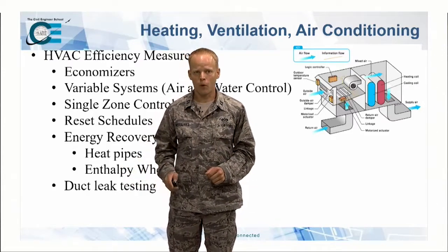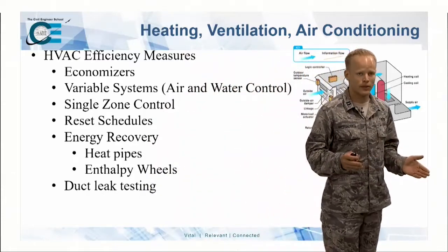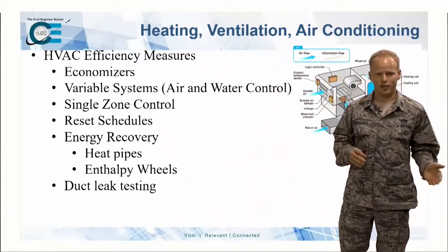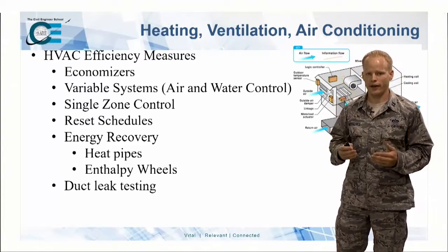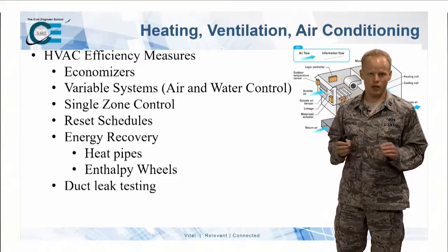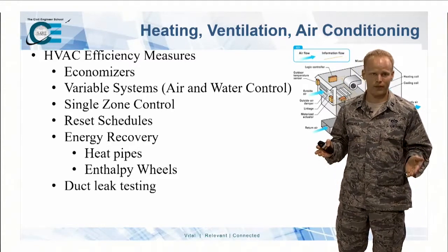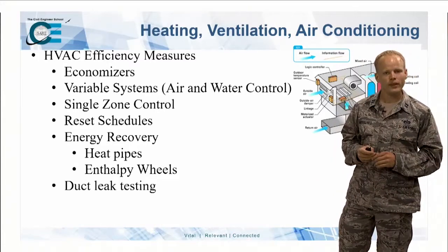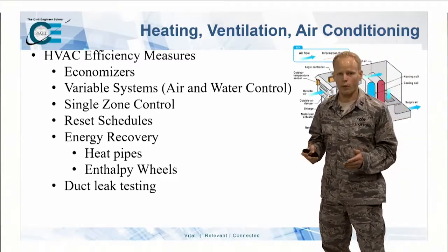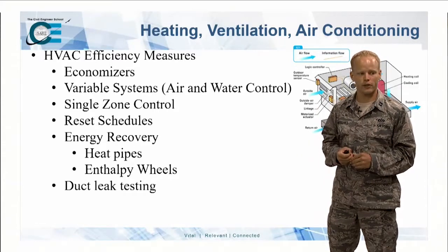Variable system. Why do we want to just cool the system the whole time at the same rate? It's going to change. Well, let's adjust our airflow. Let's adjust our water flow and we can better meet the system. Your house, probably not a variable system. Turns on, then it turns off. Variable air is what we use in the Air Force in most cases.